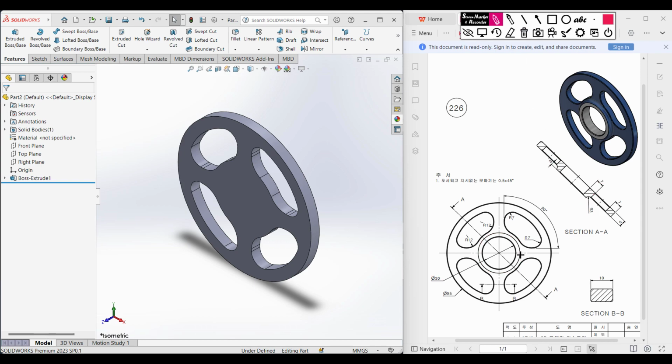So finally, after doing that, we will draw the extrude cut circle, and this inner extrude cut circle has a dimension of 30 unit. Then I will extrude cut it to through all, and finally we can see we have some chamfer. Here we have a chamfer of 0.5 and 45-degree angle, and we will give all the chamfering on the surfaces. So let's go back to our SolidWorks.